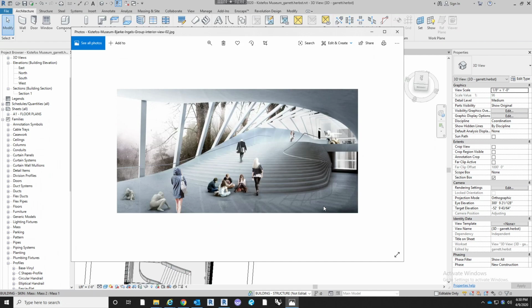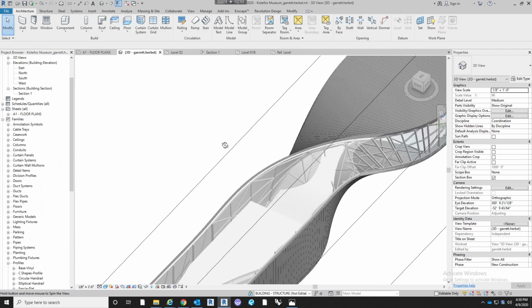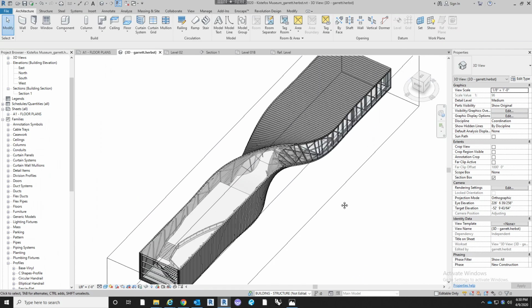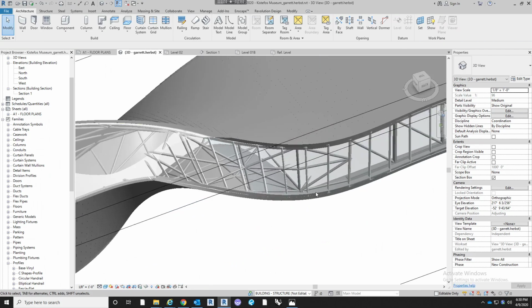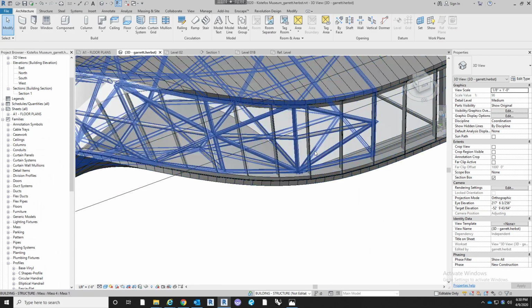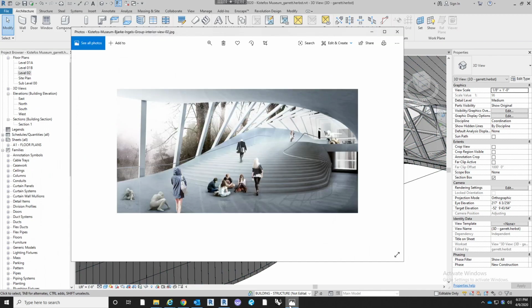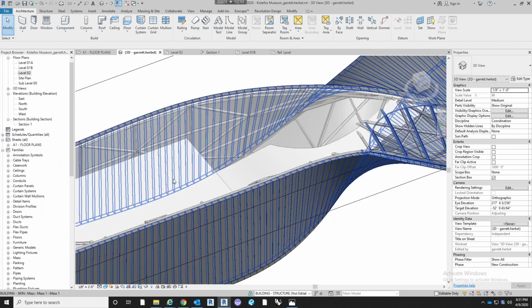We'll be using the same elements that we did before, with a little bit of a twist. Hopefully, that makes a little bit more sense. So we'll want our stair to start over here, where it is in the picture, and go up here, meet the second floor. We'll edit the profile of the second floor to meet that stair on the top. So in the picture, it looks like you got probably a 12-foot width plus this kind of cool radius. So we'll do a 12-foot stair.